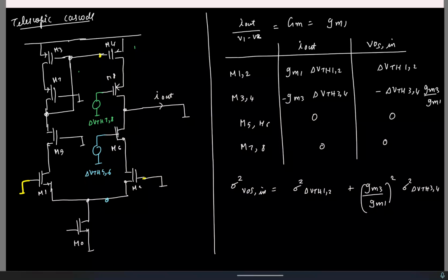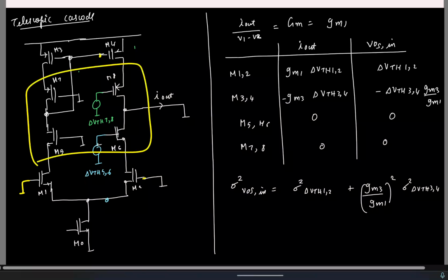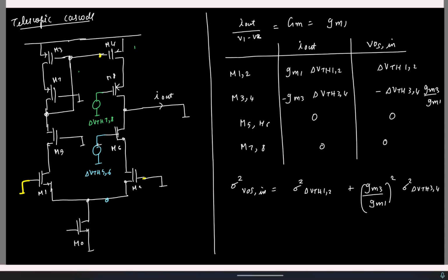Okay. So this is a nice thing because see now with Cascode I've added 4 additional transistors, but it looks like they are not contributing any noise and they are not adding to my offset. Okay, this is a nice advantage with Cascode, that the effect of these Cascode devices is very minimal. I mean, if R0 is infinity, it's 0. With finite R0, it will be very small. Okay. So we have some time. Let's finish the next configuration.